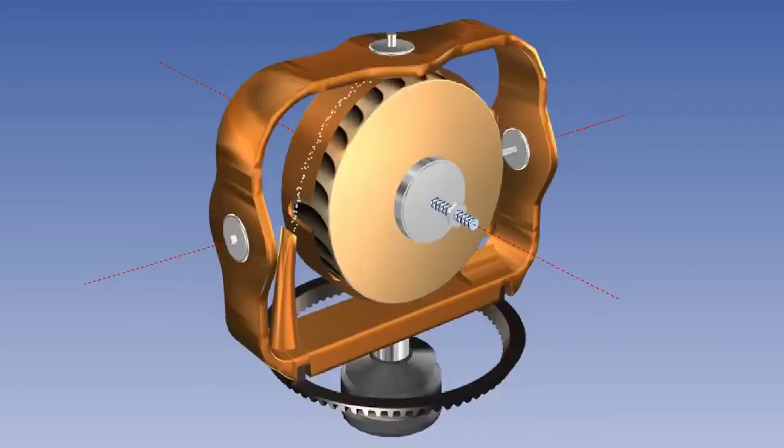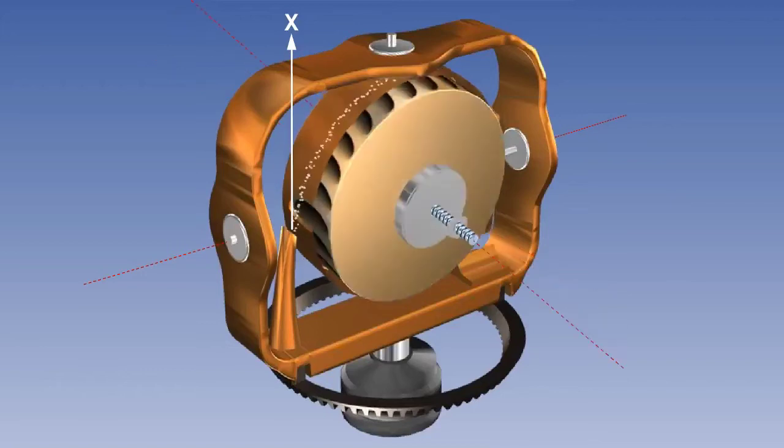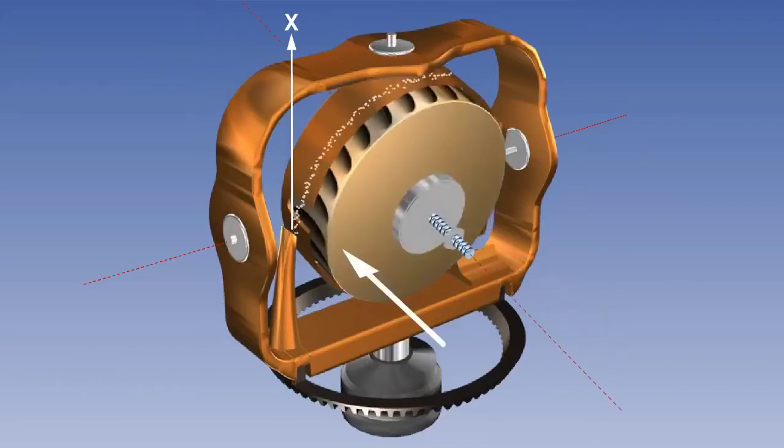The way it works is that so long as the rotor axis lies in the yawing plane, and therefore at right angles to the outer gimbal axis, the full force of the air jet will be used to drive the rotor. We will call this force X. If the gyro topples but the aircraft stays level, the rotor is no longer in the yawing plane of the aircraft, or at right angles to the outer gimbal axis.